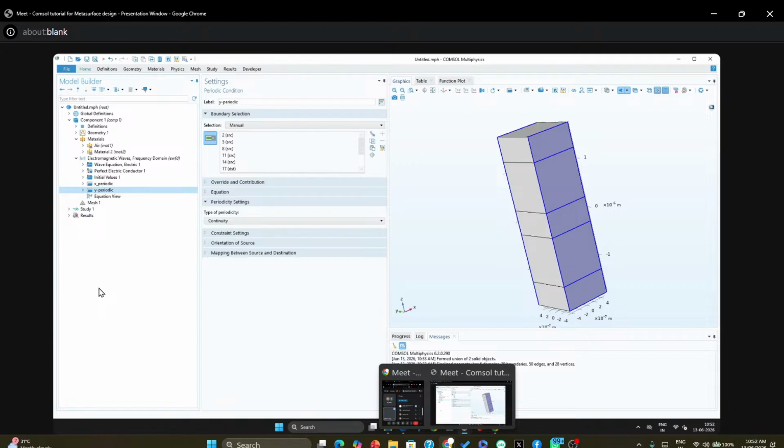So if you want only a 1D periodic boundary condition, then in the y direction you just choose scattering boundary condition or some other boundary condition, and one direction is just a periodic boundary condition. Just like some people use this nano beam structure in a waveguide, where there is a periodic hole in one direction only, so they choose only one periodic boundary condition.